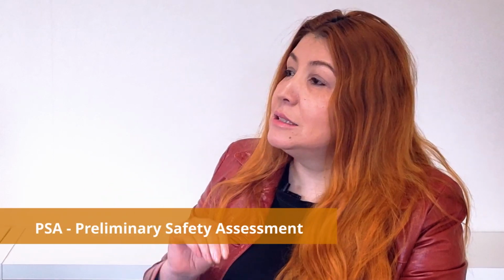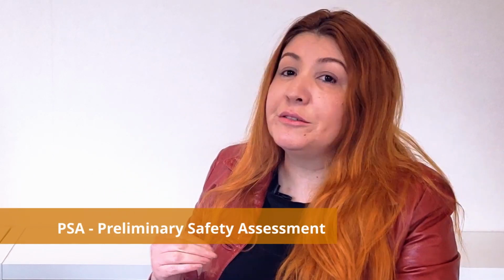Yeah, this is a step after the FHA. So as a deliverable of the FHA, we can define the function design assurance level and other safety objectives like probability of failures or the level of independence of systems. And the preliminary safety assessment is a way to verify if the proposed architecture has a potential to comply or not with those requirements.